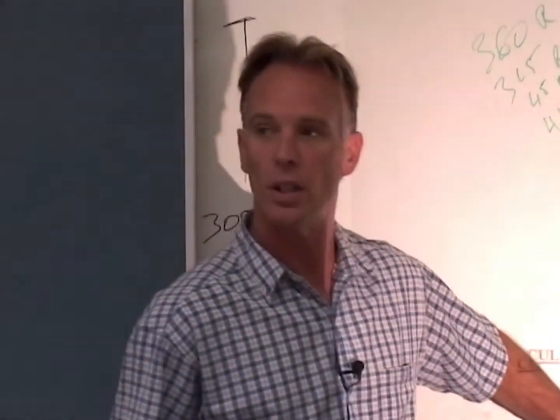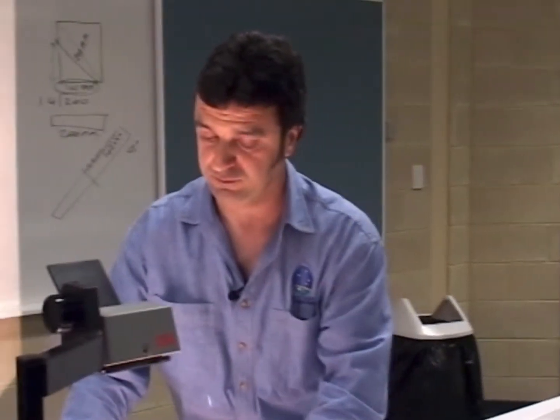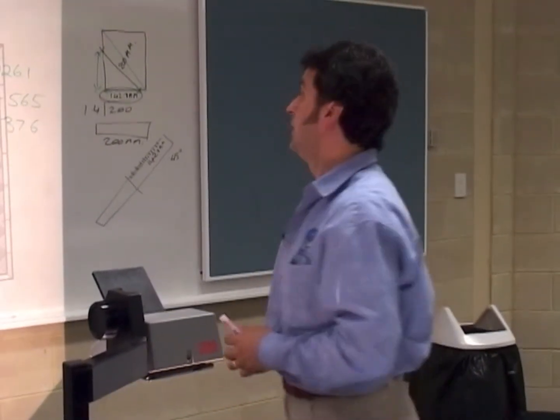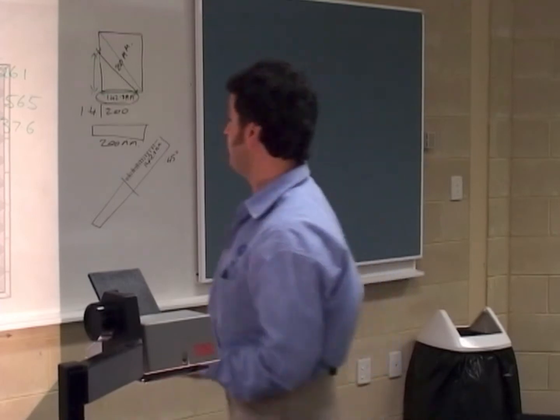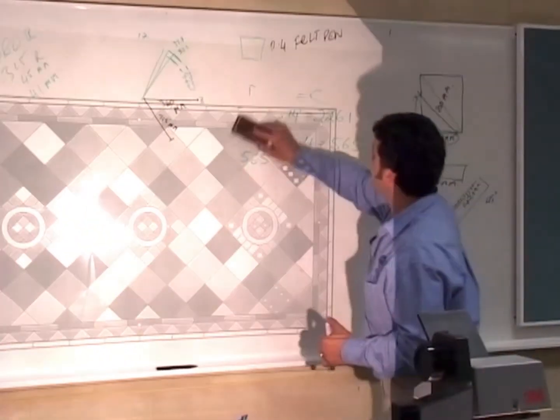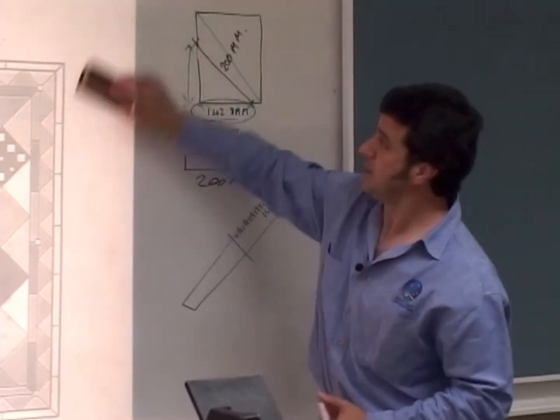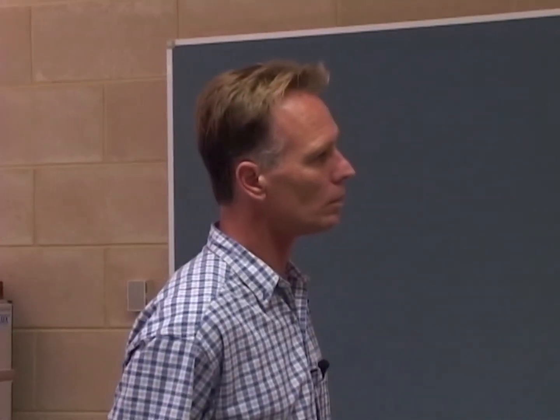Does anyone have any questions along the lines of the formula that we used, or working out the quadrant or anything like that? Will you be putting in an expansion joint because it's a commercial floor and the traffic over it and such? We will be putting in an expansion joint. If we can just slip back to this one for a moment. Does anyone remember or know what our span in terms of regulations for expansion joints is? 3 metres. For external work, 3 metres is okay.